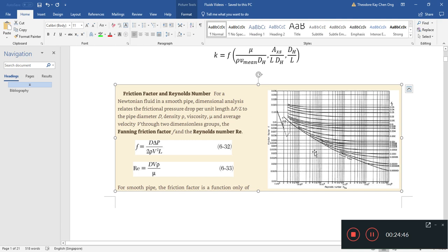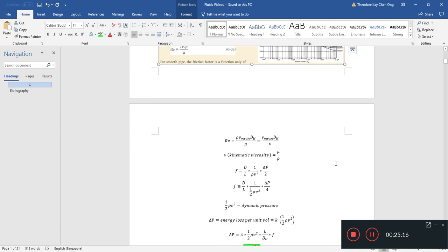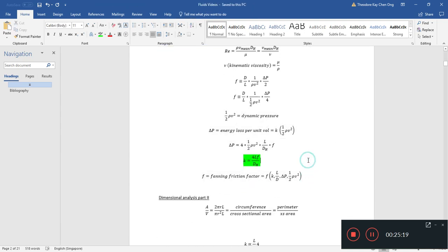If you look at the micrograph of the tube surface and you find that it's a lot more jagged, it causes the fluid to slow down more, so the surface roughness is higher. Some of the surface roughness values you can find in Perry's Chemical Engineering Handbook, in chapter 6, or other chapters if it's not there. But it's mostly in chapter 6 anyway, where fluids is. So this is how we usually talk about energy loss in the fluids context.